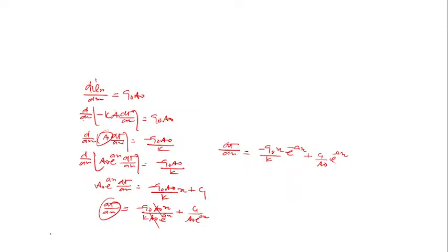Okay, one boundary condition you can use here. What boundary condition? At x equal to 0, what about dT upon dx? Anyone? 0. Why? Because no heat transfer is there, and q is equal to minus kA dT upon dx. Because the left face is insulated, and that is called an insulation boundary condition. I will discuss it in the next topic. Whenever we have an insulation boundary condition, dT upon dx is 0, that makes q equal to 0.